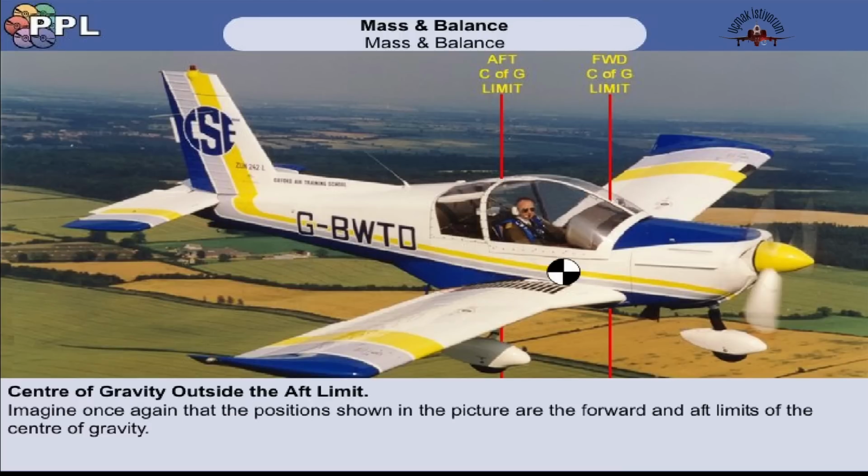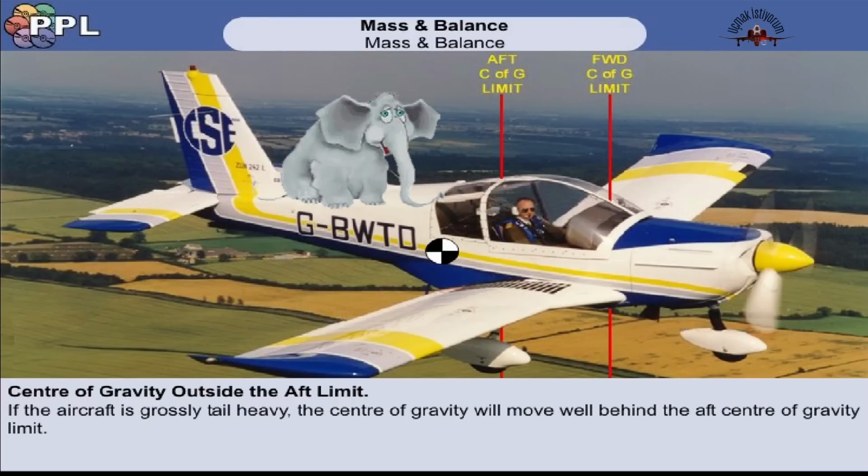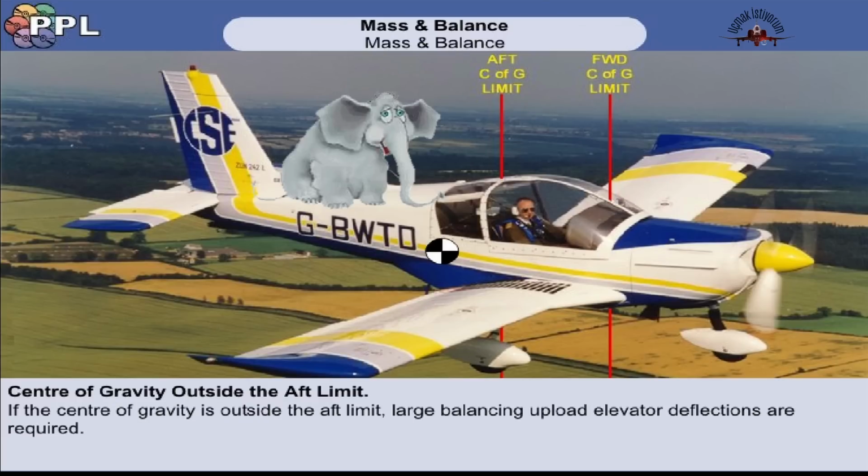Imagine once again that these are the forward and aft limits of the center of gravity. This time, though, imagine that the aircraft has been loaded grossly tail-heavy. The center of gravity will move to a position well behind the aft center of gravity limit. If the center of gravity is outside the aft limit, then a large balancing upload is required from the tailplane, requiring large elevator deflections.